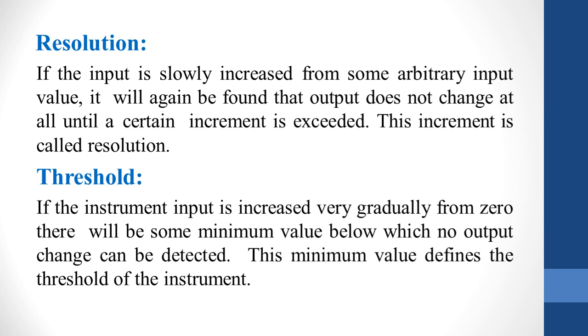Resolution. If the input is slowly increased from some arbitrary input value, it will again be found that output does not change at all until a certain increment is exceeded. This increment is called resolution. Next is threshold. If the instrument input is increased very gradually from 0, there will be some minimum value below which no output change can be detected. This minimum value defines the threshold of the instrument.